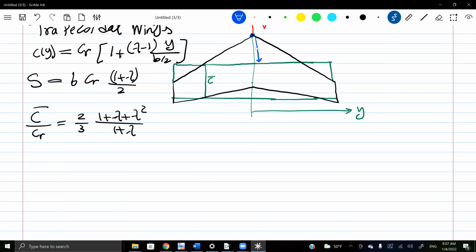And from the wing apex, I move forward along the center line, a distance called the X bar, to arrive at this point, which is the beginning of my C bar. And I have a relation for this X bar. What is this X bar? It's again in terms of C root: 1 plus 2 lambda over 12, aspect ratio, tangent of sweep leading edge.